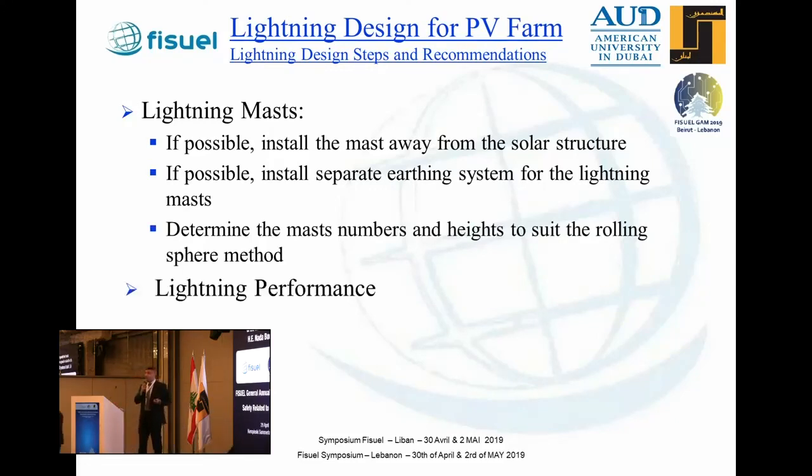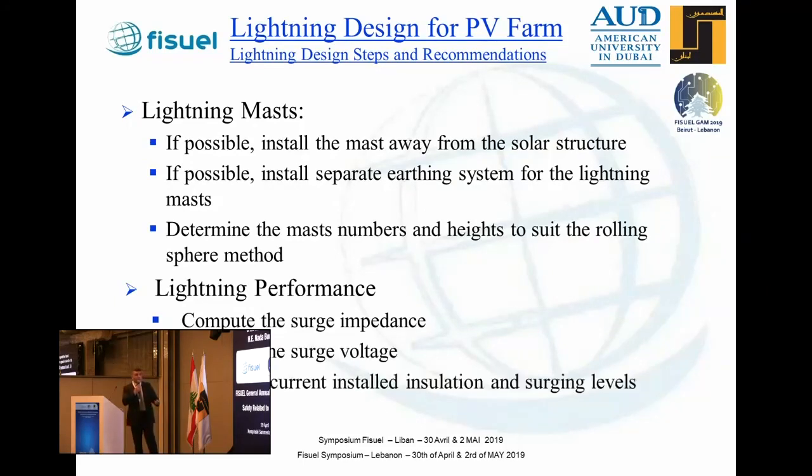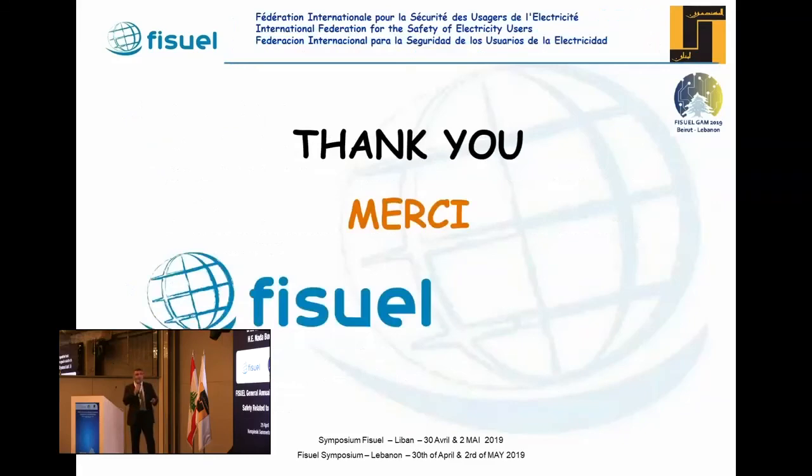And at the end, we do the lightning performance. Compute the surge impedance, compute the surge voltage, and verify that the currently installed insulation and surge level meet the V surge due to a lightning strike. And at the end, you proceed with the design report. Thank you.